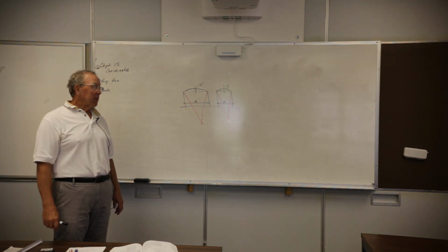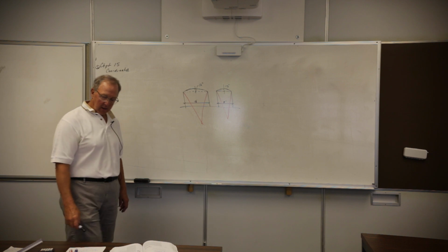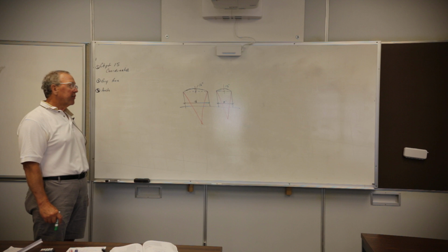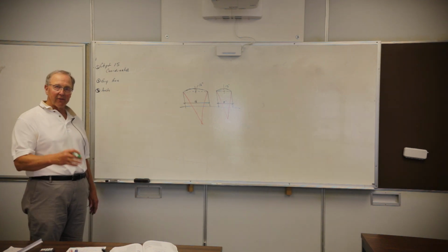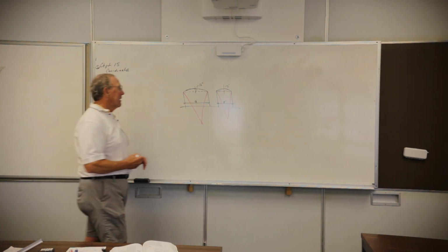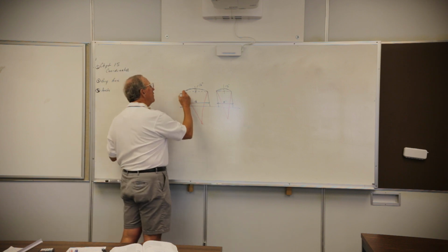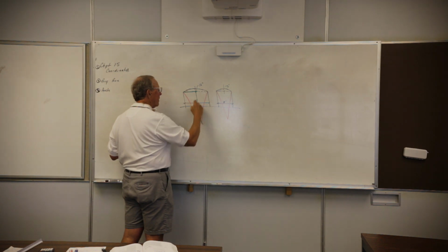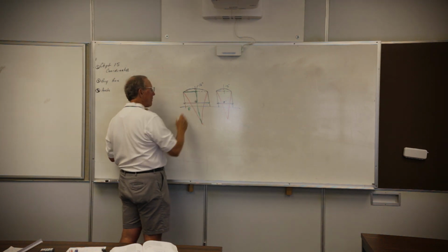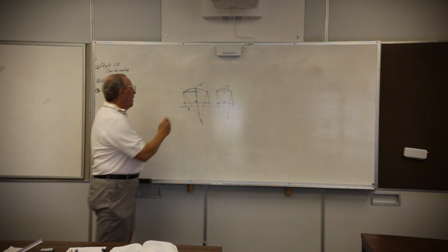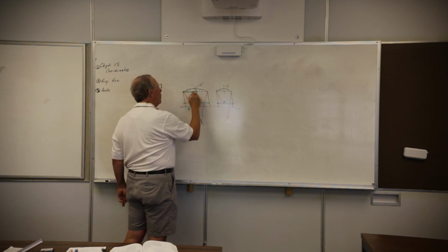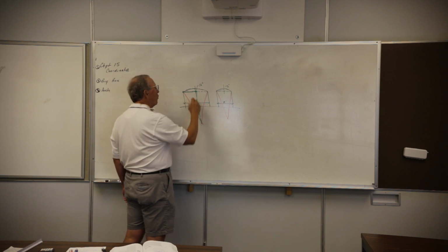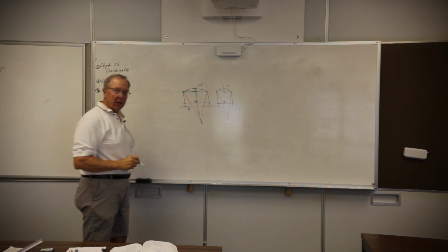answer. I'm going to show you the mathematical logic behind this, and the calculator does it. You'll find out this is not quite as easy as that 5-stroke operation, but it's still not that difficult. All we're going to do is take this guy and we're going to create a triangle. Right there. This is my radius. That's what I want. This from here to here is half the width of the arc. And from here to here is the radius minus the rise.